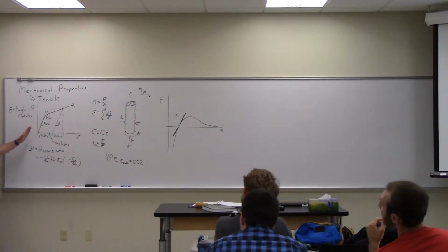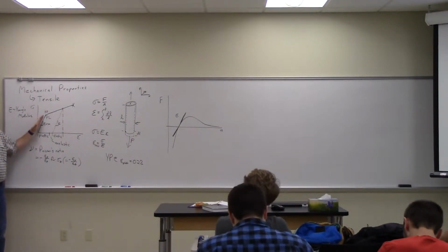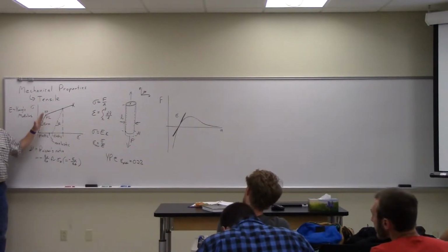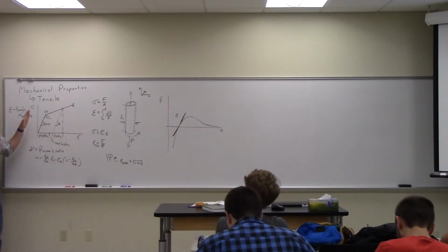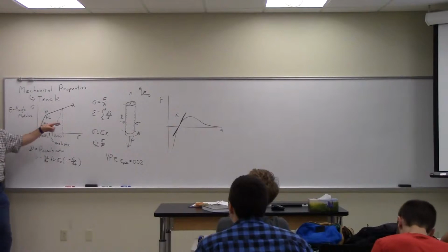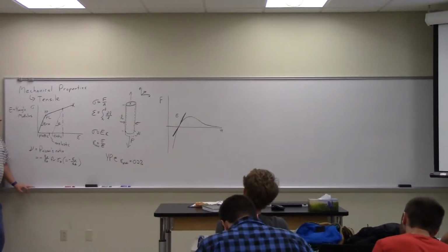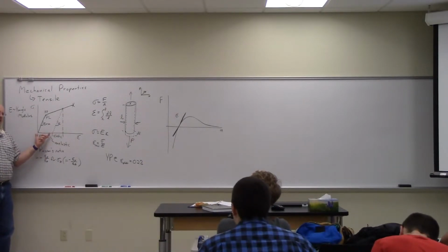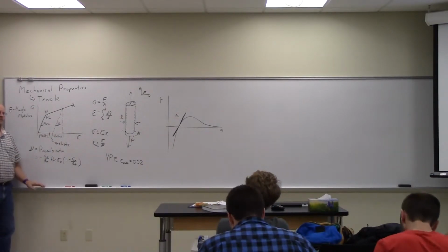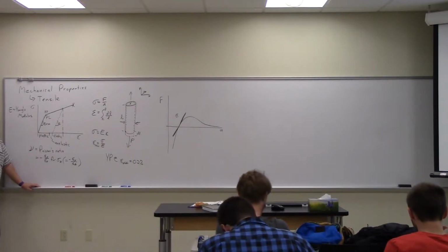In other words, where it deviates from the elastic region, when this linear region slides over by 0.2%. The horizontal scale is a percentage typically. Why is the plastic region the region on the left and the elastic the region on the right? Because when I let it go, the elastic region comes back, the plastic doesn't. The plastic is stuck. I thought it restores when it's on the left end there.